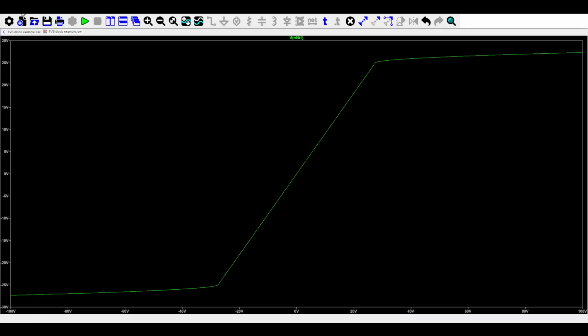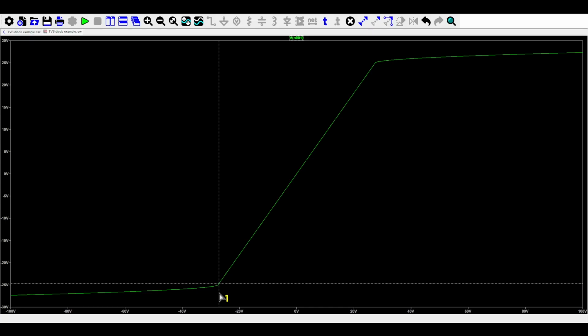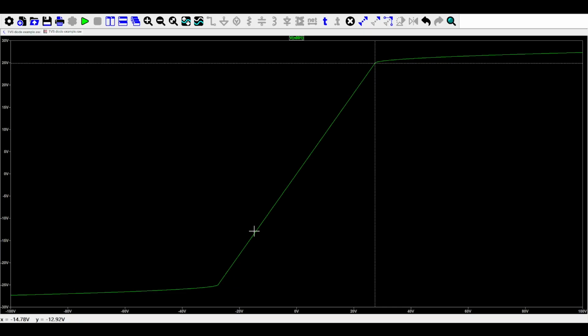I've got to actually figure out these tools. See if this will actually give us our numbers. This is about, oh, 27 and a half. And same idea. So this protects against surges that go more than 27.5 volts, either negative or positive, because it is a bidirectional TVS.